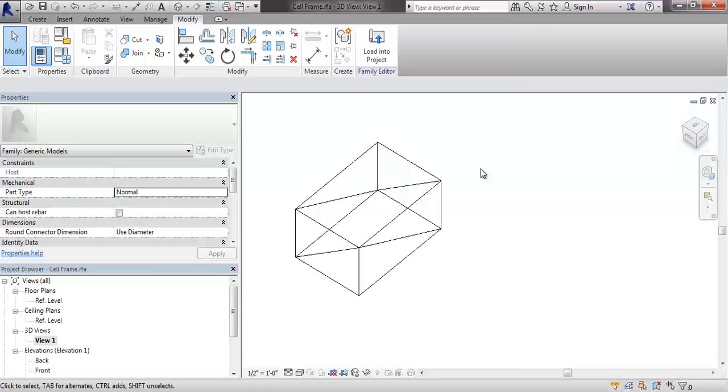Right, so then the next thing is when I draw a wall, right? A wall in Revit is just a line-based tool, right? And it's got a set of parameters. It's building a box geometry along the line, right? So we're going to want to draw this out with that line as if it were a wall. And we're going to control how many go in the north direction, and then that line, wherever I draw, is going to control however many I have this way.